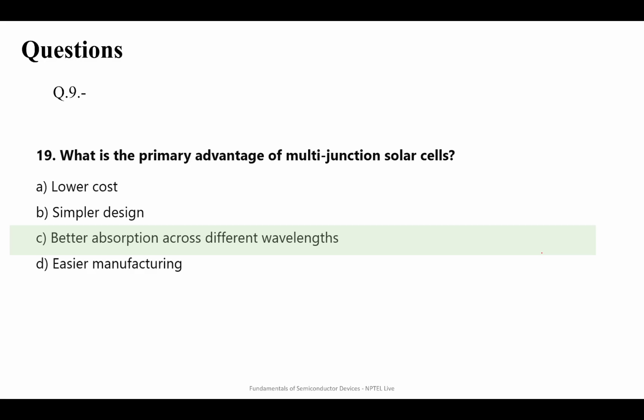Sir, one more time, a recap of the last sentence. Yeah, so silicon is absorbing everything above 1.1 eV, right? But if my solar spectrum is peaking around 2 eV, the extra energy between 1.1 eV and 2 eV is getting wasted.